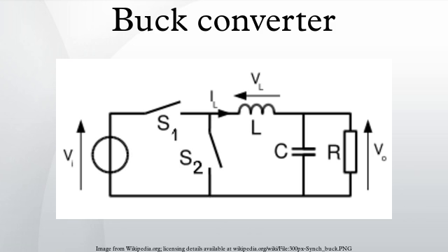There is also a significant decrease in switching ripple. Not only is there the decrease due to the increased effective frequency, but any time that N times the duty cycle is an integer, the switching ripple goes to zero. The rate at which the inductor current is increasing in the phases which are switched on exactly matches the rate at which it is decreasing in the phases which are switched off.